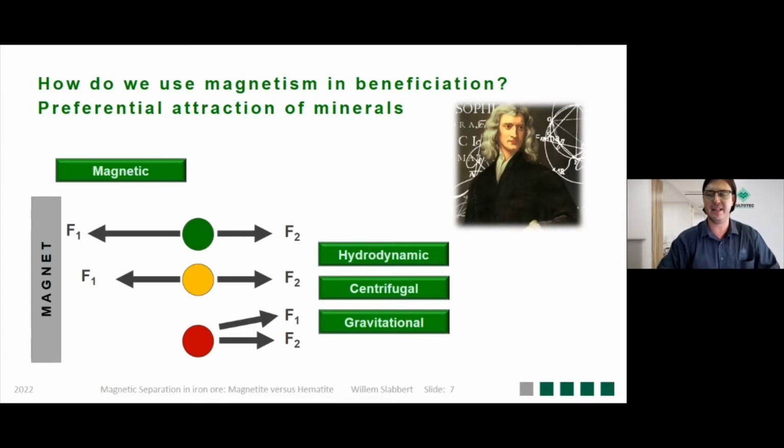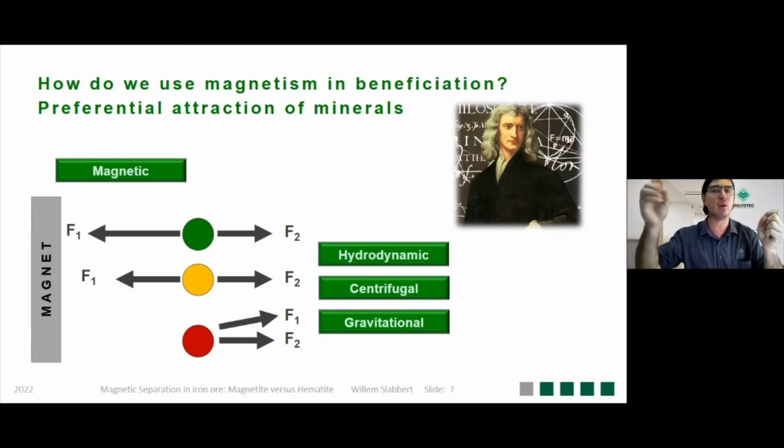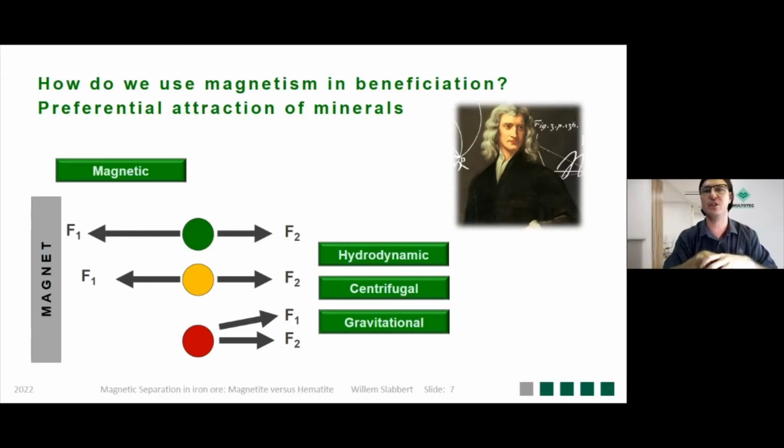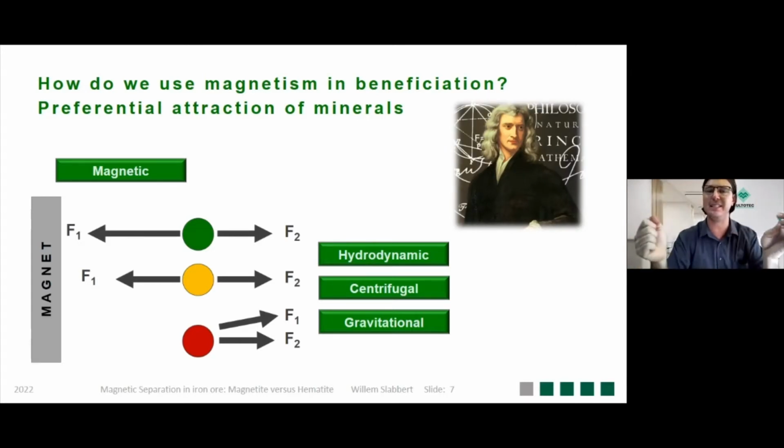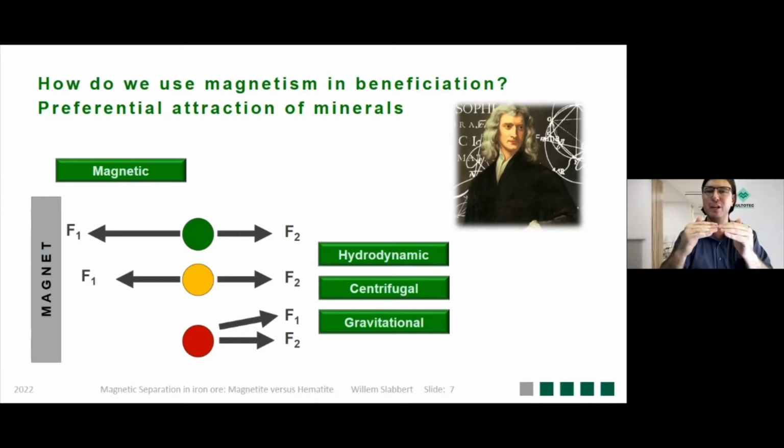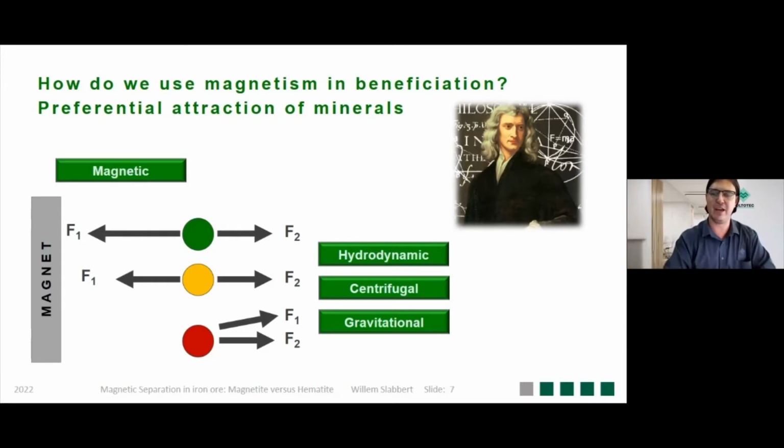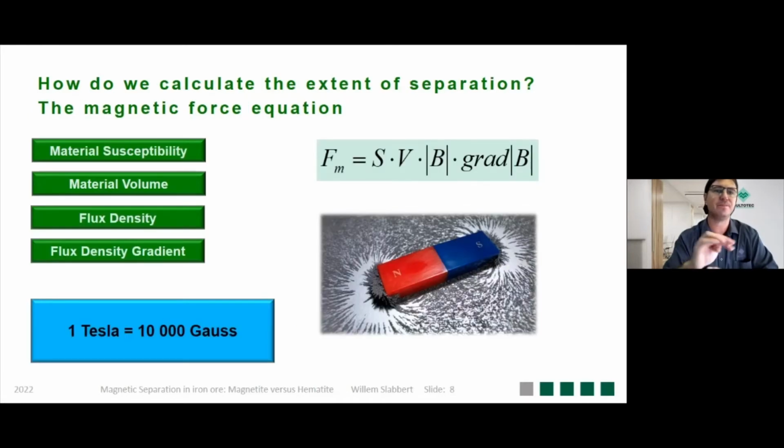In the force balance then, between the magnetic attraction force to the one side and the hydrodynamic or centrifugal and/or gravitational forces acting on the particles through the magnetic separator, would result in a different magnitude of force balance between ferro- and paramagnetic materials. We can then exert that force balance as engineers to achieve a certain property. Having particles experiencing more attraction force means that we would recover the ferromagnetic particles, but that we could have the paramagnetic particles being washed out of the magnetic separator.